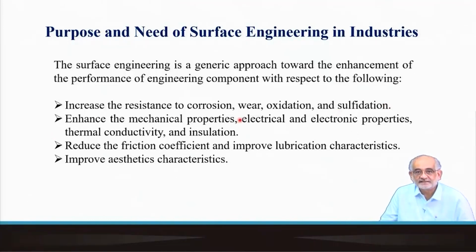It should enhance mechanical properties, not just mechanical, but even functional properties like electrical, electronic properties, thermal conductivity, emissivity, catalysis, insulation. It should also help you reduce the friction coefficient when you want that. When you don't want that, you can even make the surface rougher and increase the friction coefficient. So that means I can change the tribological properties depending on my objective. Either it can make the surface smoother or rougher.